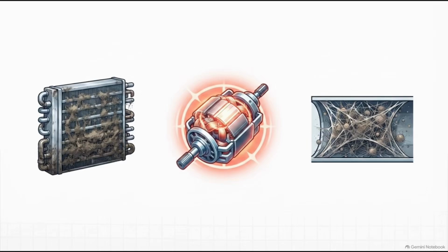Now let's look at heating. Restricted airflow from a homeowner who hasn't bothered to change their filter in a year, or maybe an inducer motor that's failing to pull enough of a vacuum.